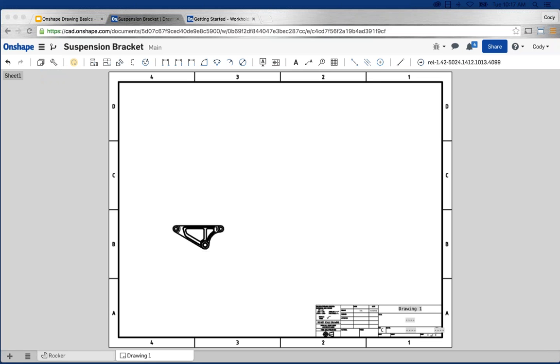A question, just real quickly. Sometimes you need an odd view that's not a standard. Can you position the part in a modeling mode and then go back to the drawing mode and paste the current view? This is a very good question. Unfortunately, I don't think that we can do this today. I think this is going to be a limitation. Now we can discuss workarounds, and it may be potentially capable of doing this by changing something in the model, for instance. But there's no dedicated function for current view insertion of a drawing view, for example.